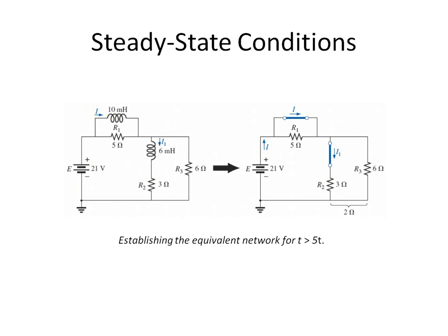Therefore, the only resistance in that path is just R2, and R2 is in parallel with R3. That is all that the 21 volts sees, R2 and R3 in parallel. R1 is not of any concern because the inductor is shorted, so all the current flows around R1, and R1 never plays a part after the inductor charges up.